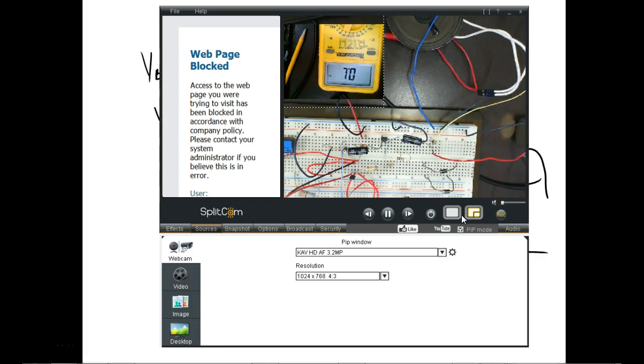But these big capacitors like this, you can actually check to see if they're good with an ohm meter. You should see them what? Charged, but eventually they'll go to what? Now this guy here is charged up to whatever voltage my meter puts out. So what happens when I swap it around, notice I get minus ohms. See, minus ohms. And then eventually it'll turn positive and charge it back up in the other direction. So it's real easy to check a capacitor.